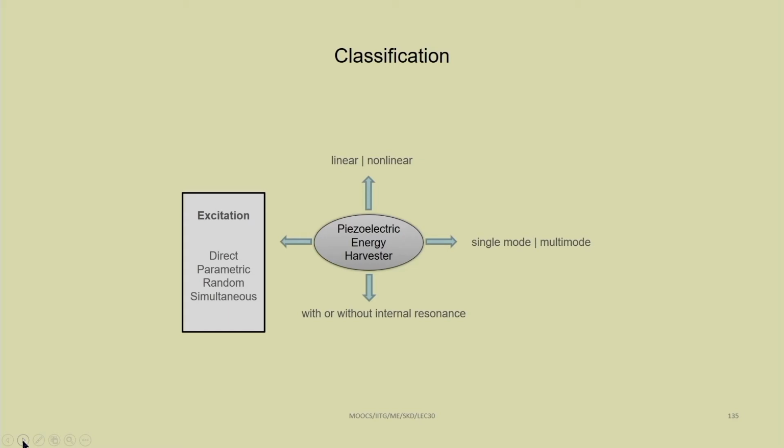Already you are familiar with the resonance conditions. For example, we have the simple resonance condition, then principal parametric resonance condition of the first mode, second mode, third mode, or the nth mode, then combination parametric resonance conditions, where we can have a combination of first and second mode, second and third mode, first and third mode. So, we can have combination parametric resonance of sum type and difference type, and in addition, due to the presence of nonlinearity, we can have subharmonic resonance and also superharmonic resonance conditions.